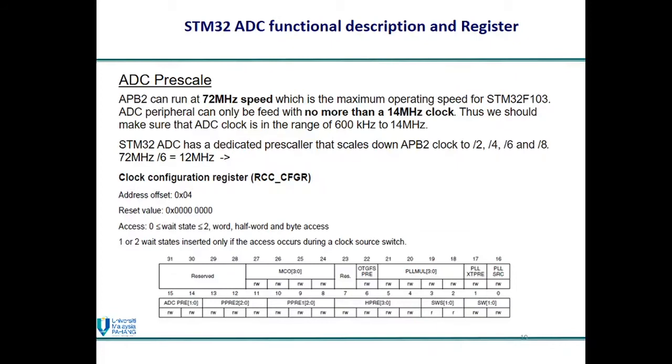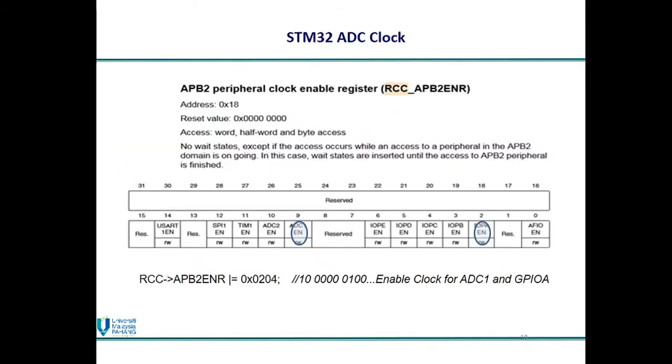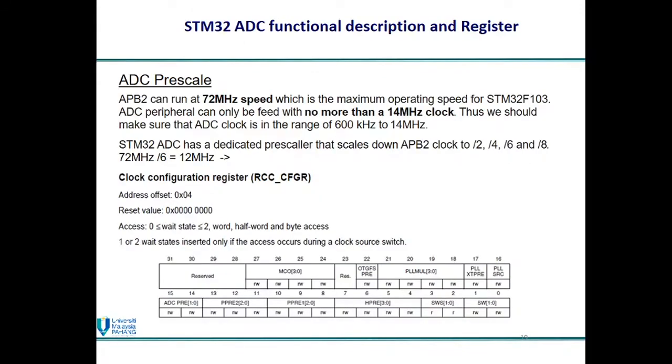When we write code using ADC peripherals, there is no need to follow any specific sequence for programming the registers. Just make sure you code the required ones correctly. Okay, let's start with the first register, that is the clock configuration register, RCC CFGR.